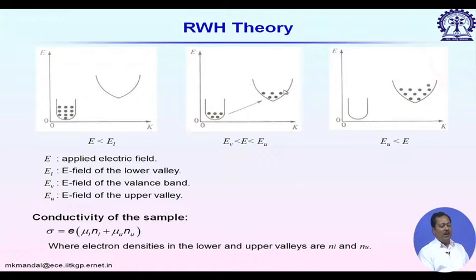Since the effective mass of the electron is high, the electron mobility is low. That means the electrons in this second conduction band, in the upper valley, have lower velocity. So, if we keep on increasing the electric field, more and more electrons will transit to the upper valley, and as a whole the overall current will decrease due to the reduced velocity in the second band.